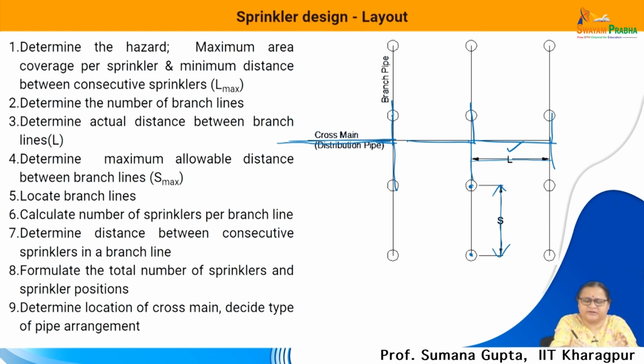and at each point you have to maintain a certain pressure. Remember, the farthest point, this point, facing this point as well as this point, will get the minimum pressure. So, we have to have a design pressure for these points, and we have to plan for the distribution. So, what does the manual give? The manual gives you the L and the S, with the dimension of this pipe, which will allow you to maintain at the end the maximum or the desired pressure.